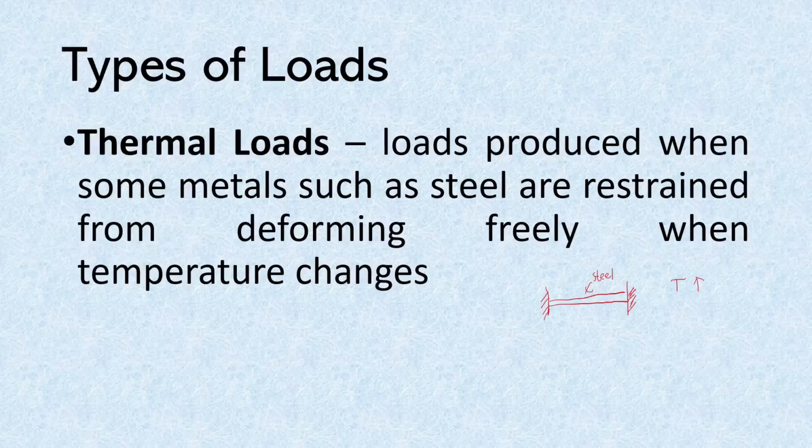If the temperature rises, then this body will expand, and so if this isn't restricted, it will elongate this way in actuality. However, because this member is restrained from moving or deforming, this portion will be subjected to stress or thermal loads. And then if the temperature decreases or declines, then this will shorten. Let's say this way. It will actually shorten at this distance, but since it's restrained from moving or deforming, this part will still be subjected to stresses.